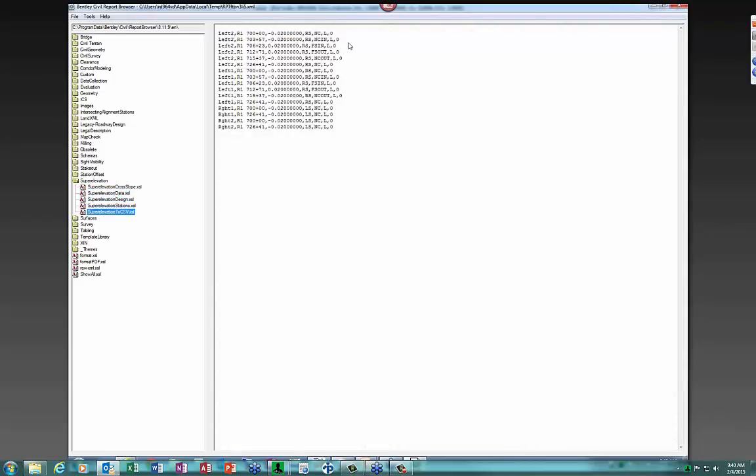If you need to provide this, or let's say you need to revise some of these stations, or provide it as an input file, instead of having the software calculate it, maybe you've got some specific transitions, or you have someone that calculates the superelevation that comes up with all the other transition stations and values, all you'd have to do is go to this CSV file format.